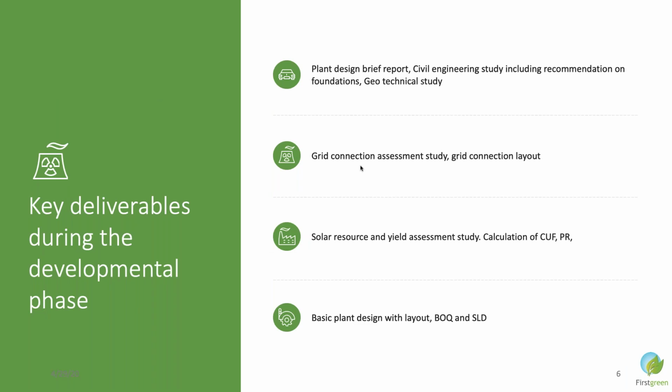So the key deliverables in this phase, that is the developmental phase, you will have your plant design brief report, that is basically your sort of DPR more on the technical side, as well as a DPR level work which you can submit to your lenders. You will have your civil engineering study, you have done your contour survey, you have given recommendation on foundations, you have done your geotechnical studies. In this phase, you will be doing all these type of detailed studies to be done at this site.